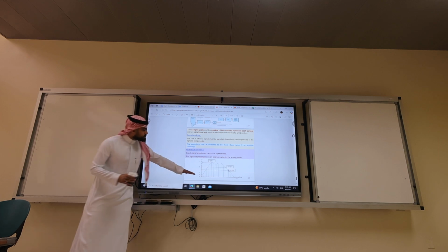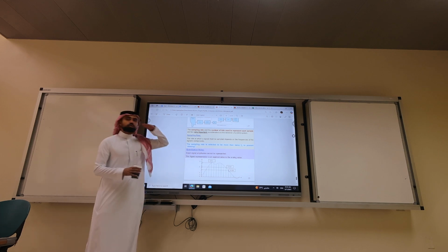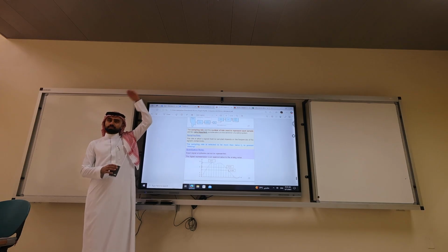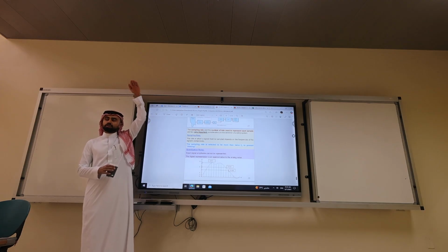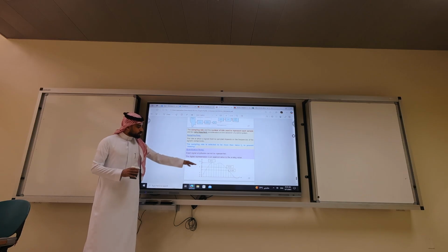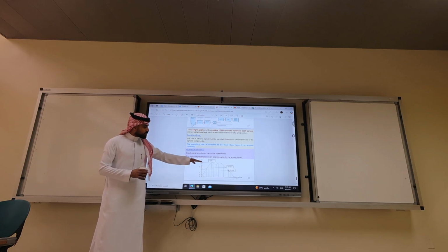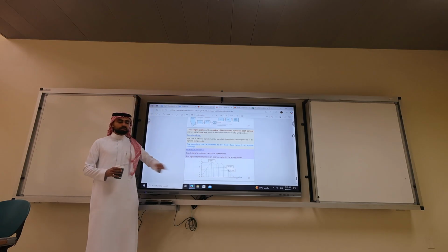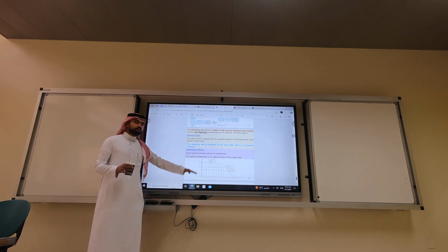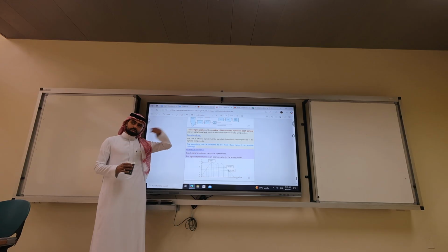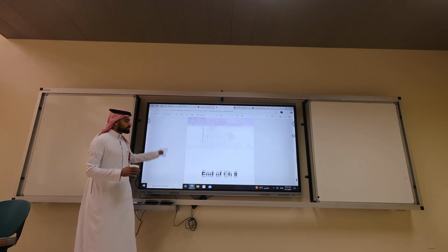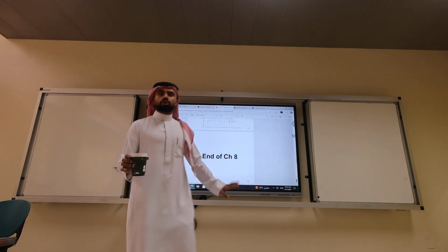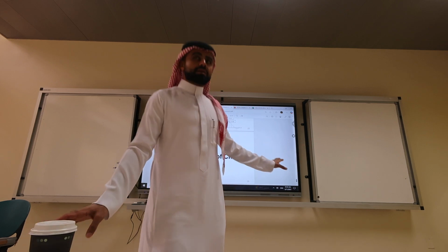Also, quantization noise. You need to define proper digital amplitudes. You can't have just 0 and 1. So in this case, for example, you need to have something for 8, 5, 4, 3, maybe 8.5, 5.5. Depending on the range, you need to define how many quantization levels you have in your analog to digital converter. With that, we conclude this class.